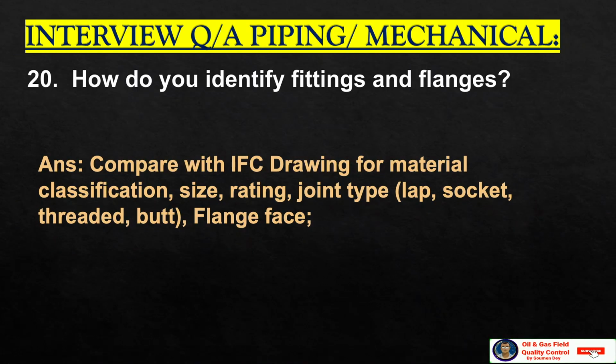How do you identify fittings and flanges? Compare with the IFC drawing for material classification, size, rating, joint type, lap or socket, thread, butt, flange face, etc.